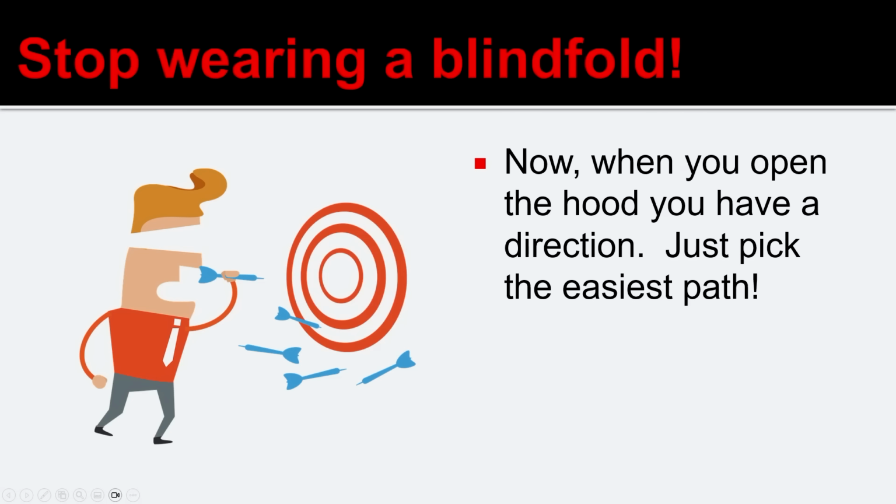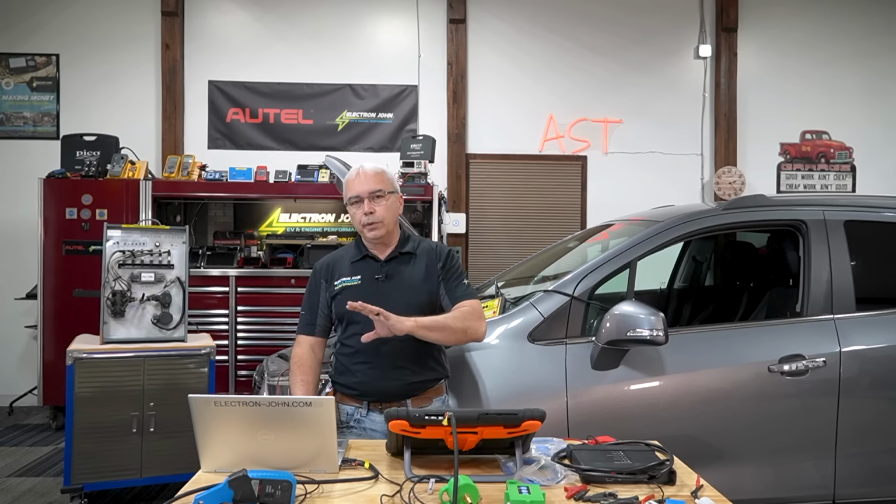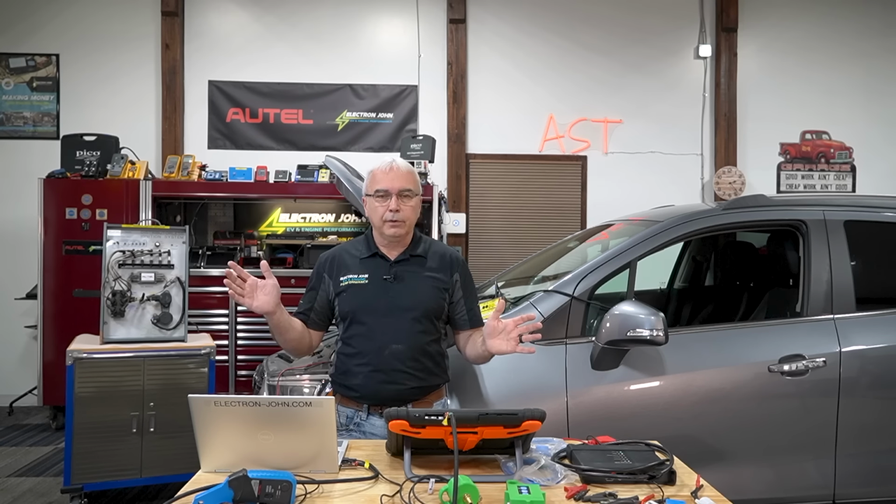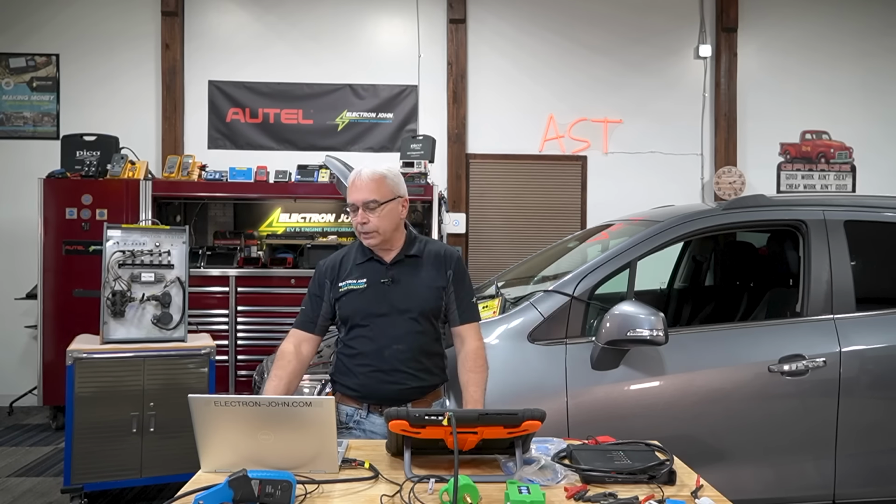And if we understand this, right, so if I looked at the scan tool while I'm sitting in the driver's seat and we use that complaint of, hey, it's running rough, whether or not there's a P0300 code associated with it, it's either going to be fuel or it's going to be engine breathing capabilities, we'll call it, or it's going to be ignition. So which series of tests do I want to pull from my diagnostic arsenal to get to the root problem here, right? And then I want to do them as quickly and efficiently as possible that gives me the same type of test results here. So now when I open the hood on the car, it's not like I'm wearing a blindfold and have no diagnostic direction to go into.